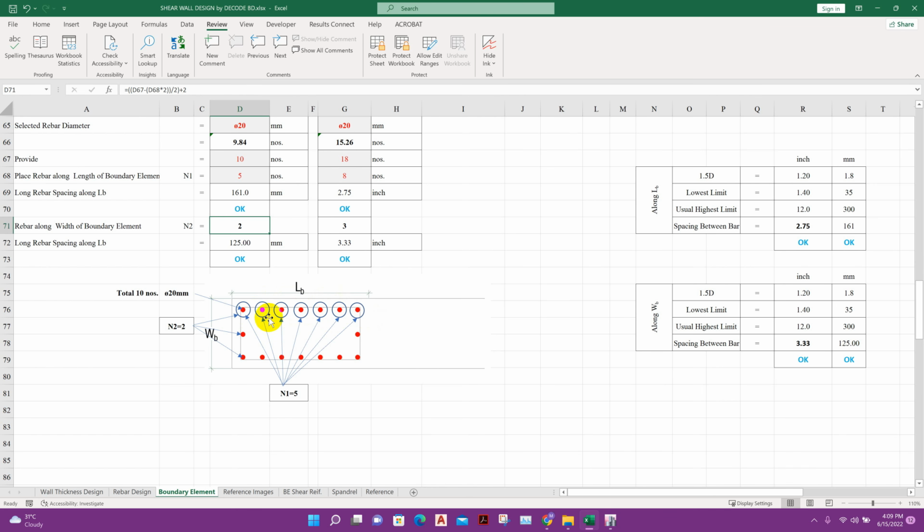So if alternate is 2, then here is one leg, these two skip, and here another leg or cross tie, then these two skip and here another leg. If we provide the alternate number as 1, then it will alternate only one bar. Here will be one cross tie, this skip, then another here, this skip, then another here, like this.